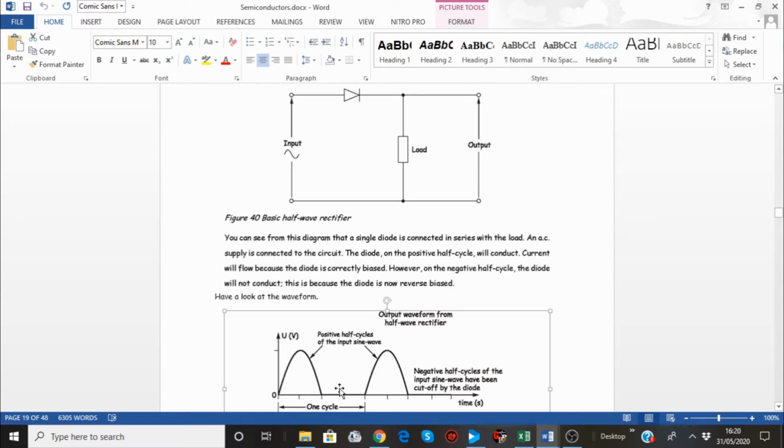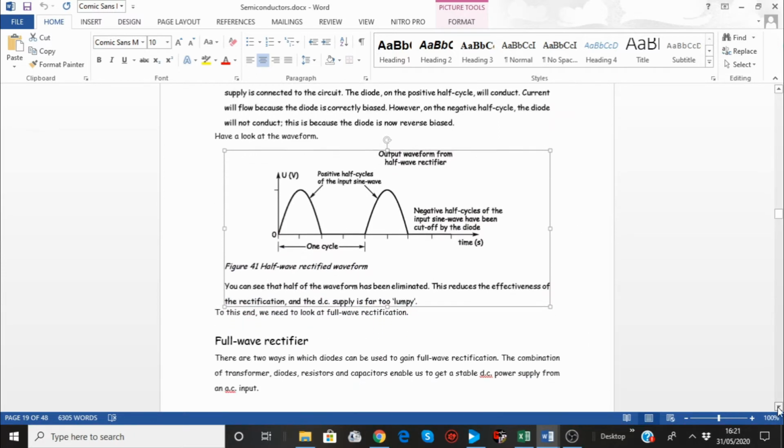First of all, you've lost part of the AC and it's varying. It's not fixed voltage. But industries use these as voltage drop, voltage reducers. Because you lose half a cycle, you're basically dropping voltage to half. You can see in some equipment, like an electric blanket, one diode is used in the switch, because they want two settings of heat, full heat and half heat, or motors, for instance, with full speed or half speed. So that's still useful.